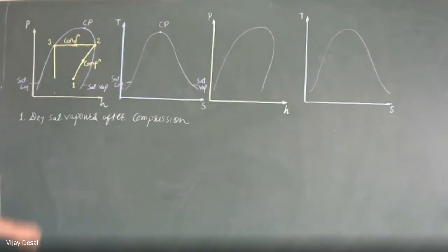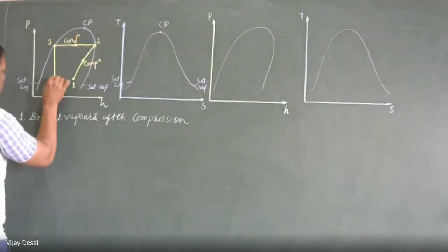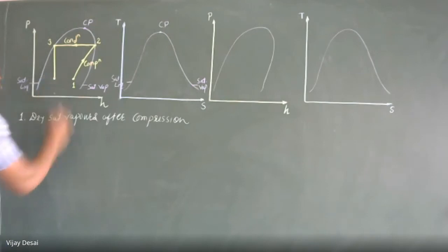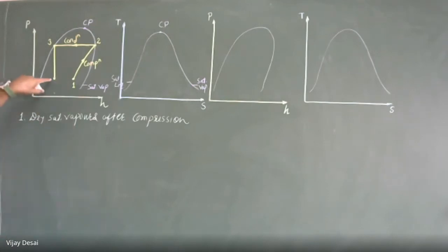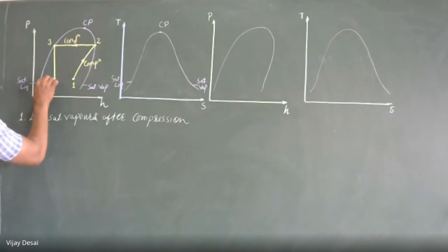And at the outlet of throttling, no doubt, it is low pressure. Pressure is high before throttling. During throttling, enthalpy remains constant, and that expansion device or throttling valve reduces the pressure. So pressure is reduced at the exit of that expansion valve. This is point 4.